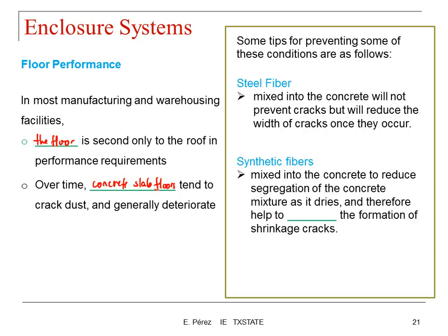Some tips for preventing some of these conditions are as follows: steel fiber, which can be mixed with the concrete. This will not prevent the cracks, but will reduce the width of the cracks once they occur, so they will not go above 1/8 of an inch.